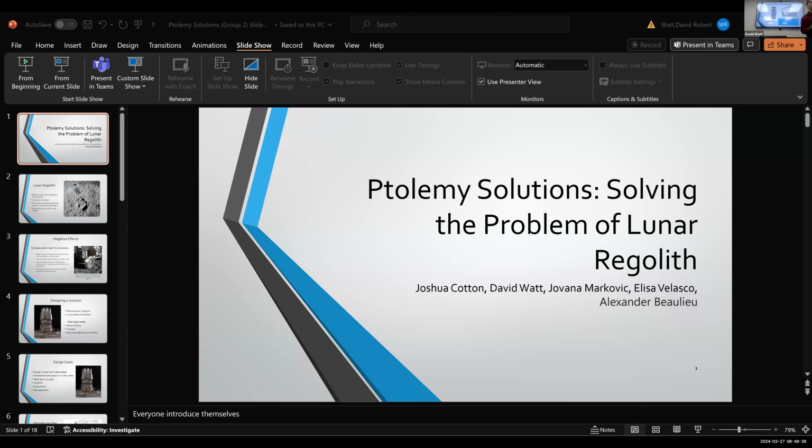Now, looking at the railing itself, this is made of aluminum 6061. It is entirely fastened by blind rivets. It has a mechanical release, and this is a render without the top of the containment. As you can see, the release, which we'll get into in a sec, is a mechanical release of the capsule itself, driven by the power of the lunar lander itself. So this will be connected to the power of the lander through the lander's payload. The payload bay, which is the top section of the Blue Origin lander, is where this railing system will actually be connected.